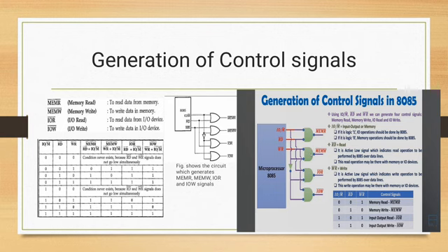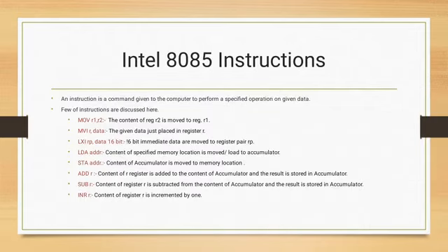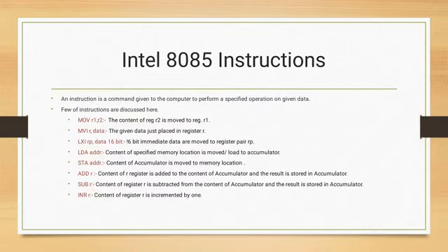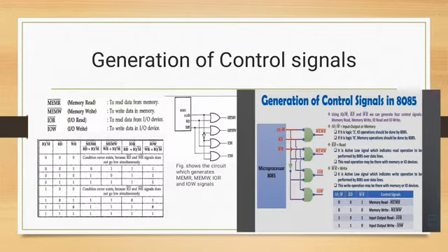That is why these are known as active low signals. If we follow this truth table, whenever we apply the combination 001, MEMR, that means memory read operation, will happen. Whenever the combination 010 is applied, the memory write operation happens, and for 101 input output read and 110 input output write operations are done by the processor.